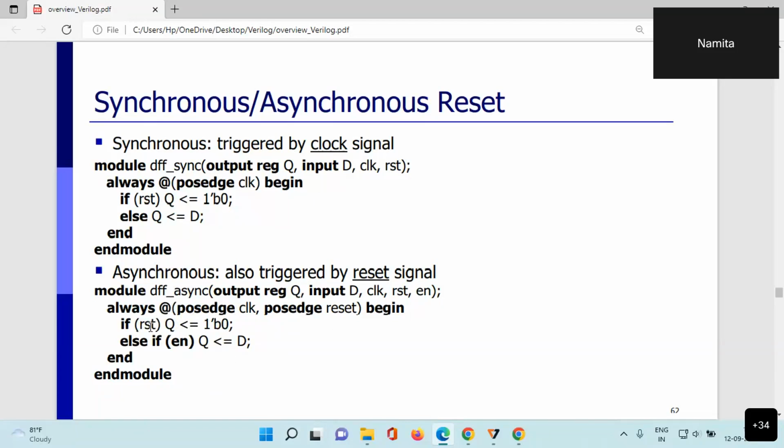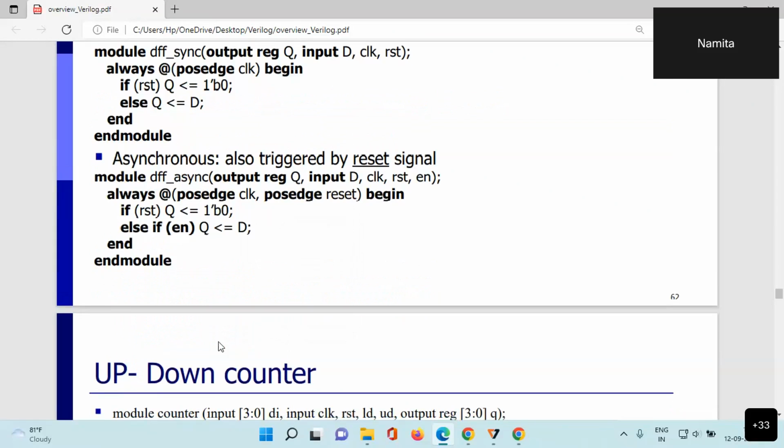That checking of reset will make that signal a level signal. It is not the synchronizing signal. So the synthesis tool will understand what is the last assignment: else if enable is 1 will happen at the posedge of clock, not this one. So this is the difference between synchronous and asynchronous signals or inputs when we are designing a D flip-flop.